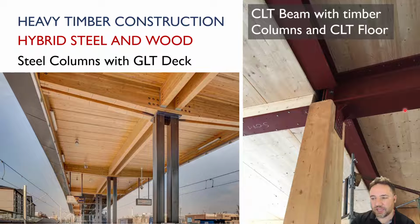but a really nice attractive wood roof with glulam beams and what's called a GLT deck, which is a glued laminated timber, like CLT but only in one direction. And on the right, combining the other way around, making the columns and slab glulam and CLT, but with steel beams to probably increase the span or stiffness or something like that.